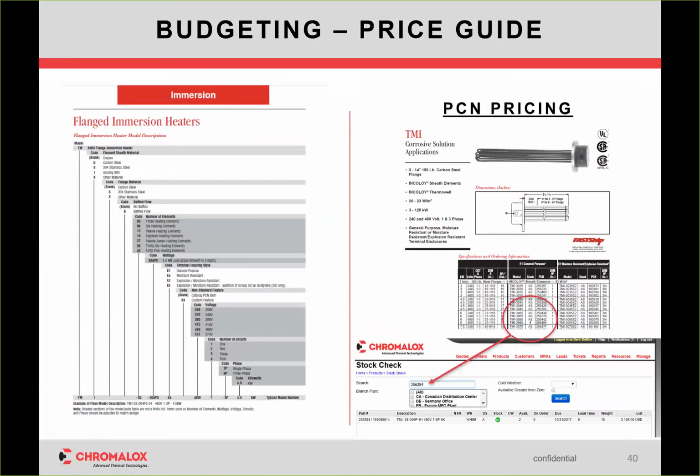I mentioned before that the cost and price is really correlated to the physical size of it. The one I selected is only 33-inch immersion length and 6 kW. You could bump up the watt density. In the case of this one, it's 23 watts per square inch, so let's double that. Let's make it a 12 kW heater. You've got a 6 kW and a 12 kW heater. Physically, they can be the same. And it's good to be conscious of that, because the customer would look at it and say, well, it's a 6, I should pay much more for a 12.